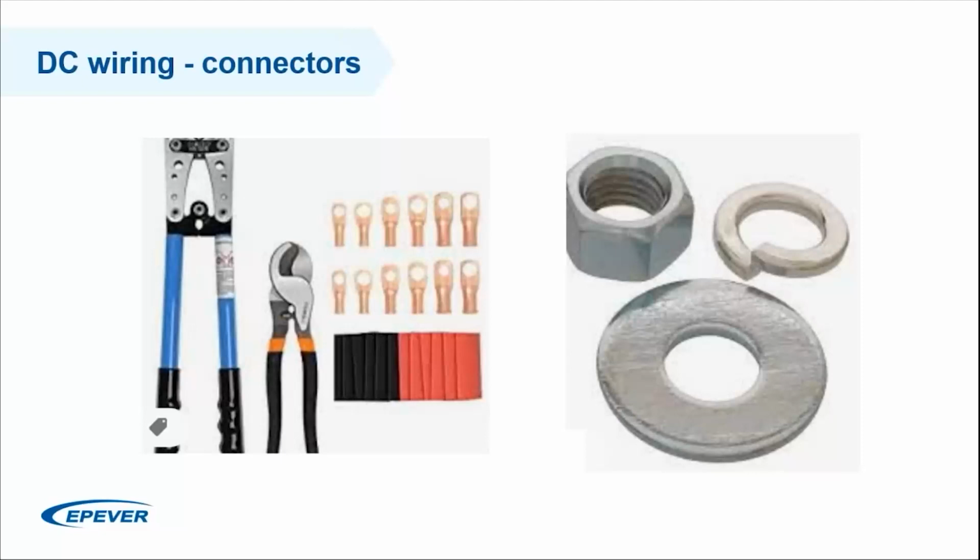So if you tighten one too much and the other one a little bit loose, then the area that the locks connect to the bus bar is not the same, and then there is a difference in the resistance level, and this is called the improper balancing of your batteries, for example. So it's better that you apply the same cable length and the same torque and the same sort of connectors, washers, nuts, and springs, and everything should be the same between the batteries, so that all the batteries actually see the same resistance towards the loads, towards the inverter, and the components that resist.